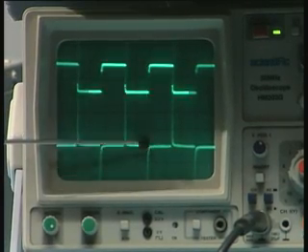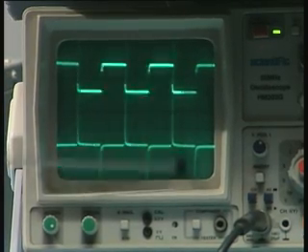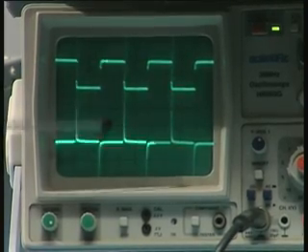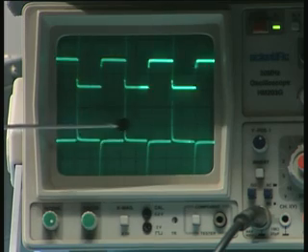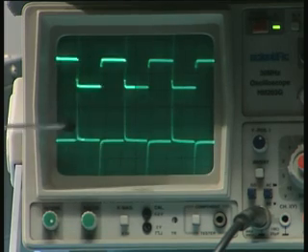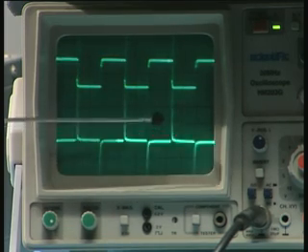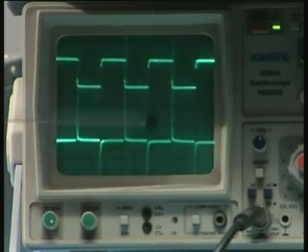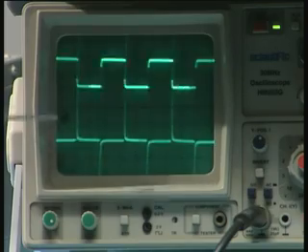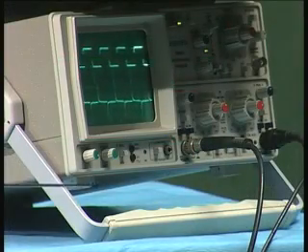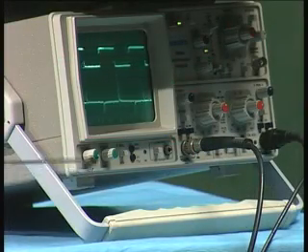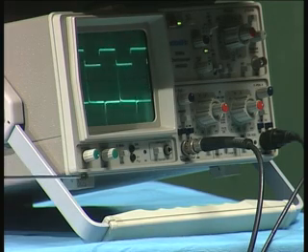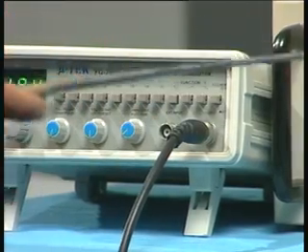So this is the output waveform with sharp spikes corresponding to these transitions from high to low, and the square wave therefore gives me very sharp pulses. If I put a diode, correspondingly I can get rid of either the bottom pulses or the top pulses, and I can use it for triggering other circuits. Now you can also see that as I change the frequency, the output also changes. If I reduce the signal amplitude, the output will also show slight variations.